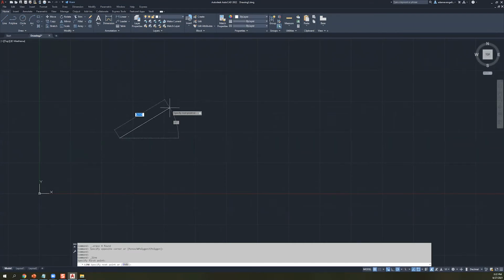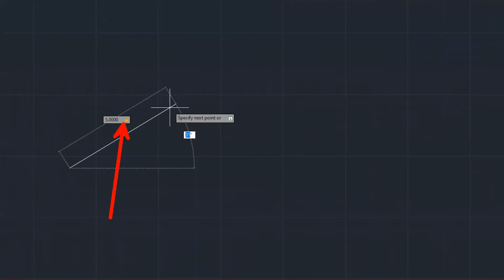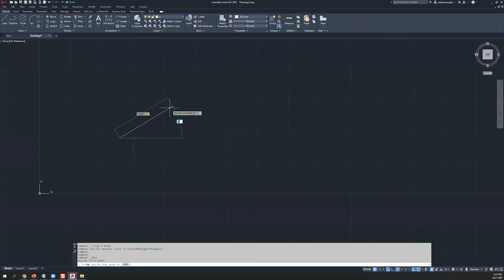So let's say I have a length of 5 or something like that. Then I could hit tab and go to the next input, and you'll see that in fact, 5 gets locked into place, while my bearing direction doesn't. That means I could keep moving around, and now I just need to specify the degree. If I don't like that, I could just go back to 5, actually meant 6, and then switch back to something else I could keep rotating, in a similar way.